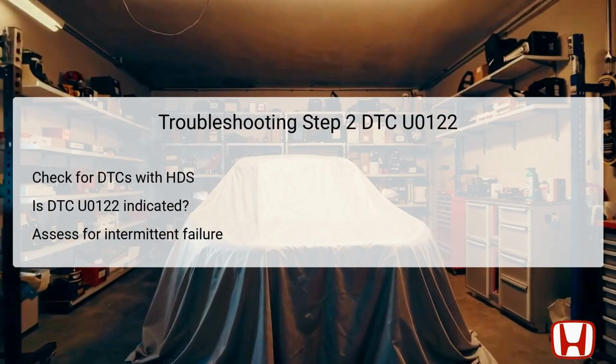If this specific DTC is indicated again, it suggests that the communication issue persists, requiring further investigation. If the DTC does not reappear, it may indicate an intermittent failure, meaning the communication line was temporarily functional at the moment of testing. In this case, one should check the ECM, Engine Control Module, or PCM, Powertrain Control Module, and VSA Modulator-Control Unit for any DTCs, as sometimes communication issues can mask other underlying problems.